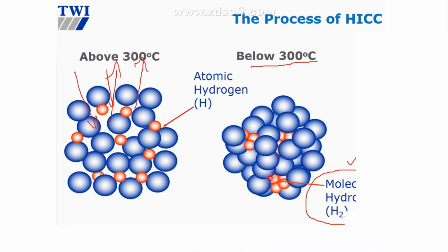When it becomes trapped, then they find a way to break the grain and then escape. That will take about 48 hours up to 72 hours. So that's why they call it delayed crack. Because it takes longer time to break the grain from inside. Break the grain and then escape. Got it?